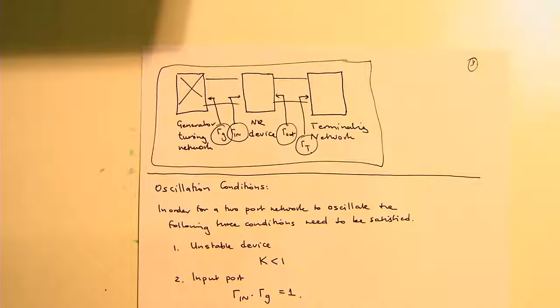Usually, tunnel diodes are fantastic because if you really want high-power, high-performance oscillators, tunnel diodes are phenomenally good. But why don't we use them in practice? Yeah, they're expensive. Industry wants to put everything on the chip. They don't want an extra separate device, because if you put it on your chip, you can make it cheap. Level of integration, etc.